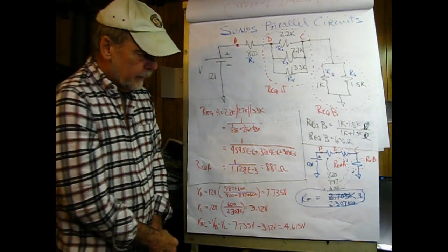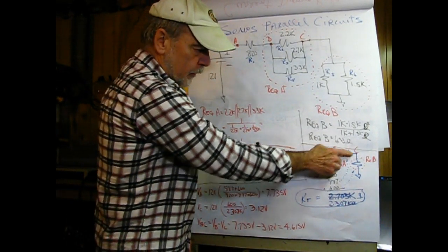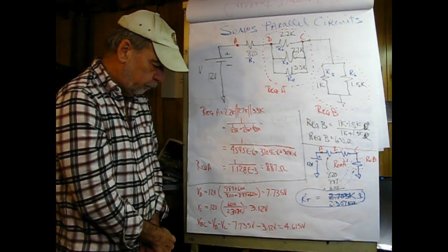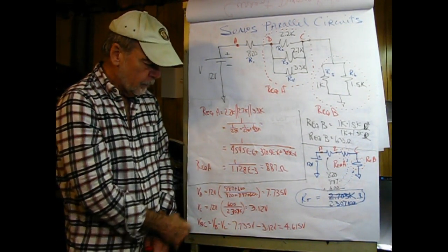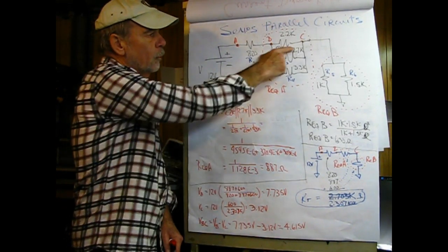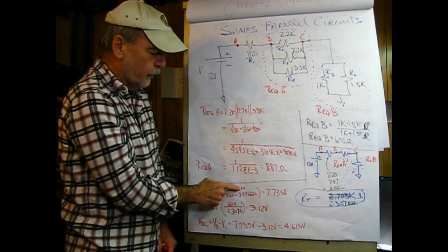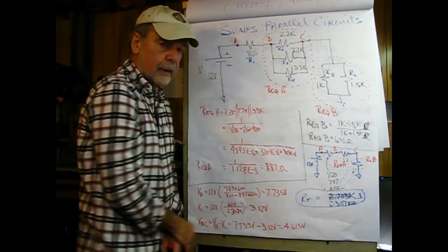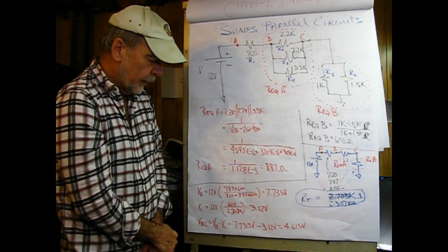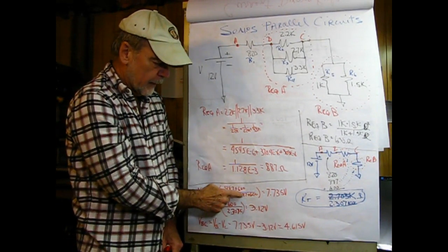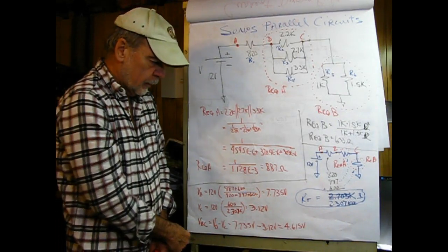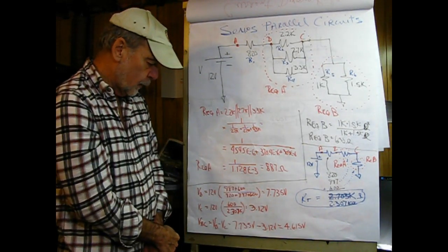So once we know that, and we now have this circuit with VB and VC of interest, it's just a matter of using the voltage divider to find what VB is. Note in the numerator I have the 887 ohms, which is this, in series with the 600 ohms, which is this. So the numerator consists of those two terms relative to ground, divided by R total, which I've explicitly written down as the 3 terms here.